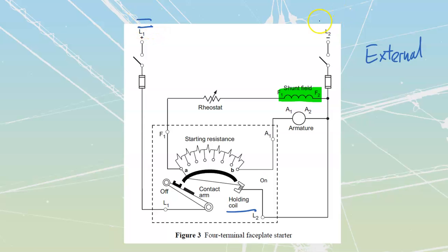We would have a set of contacts upstream that would be connected to this thing that would be tied to that centrifugal switch. So if that centrifugal switch were to operate, we'll just draw a little symbol for a centrifugal switch over here. It's going to be an arrow that goes between 2 points like that. If it were to operate, then it would kick out this coil and open those contacts. But we'll leave that alone because it's not necessary for what we're going to look at over here.